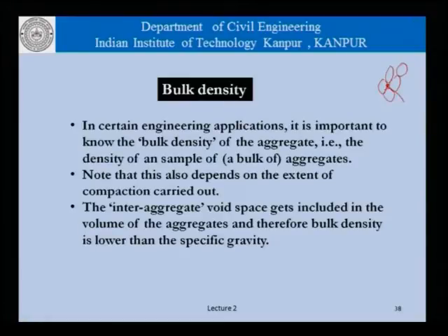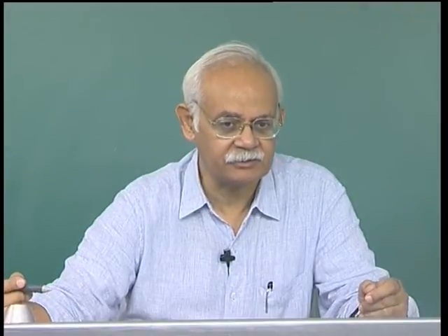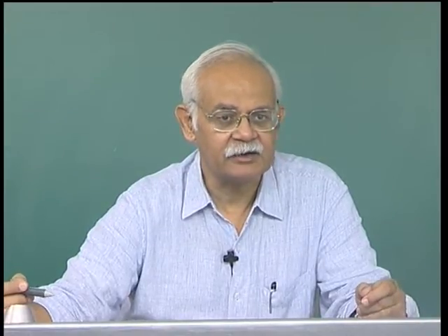So, we talk of two types of voids in an aggregate system. One is the intra-aggregate void, that is the void that we showed in the previous slide, which is the voids present within aggregate particles. And then there is inter-aggregate voids, that is the voids which are present between aggregate particles.